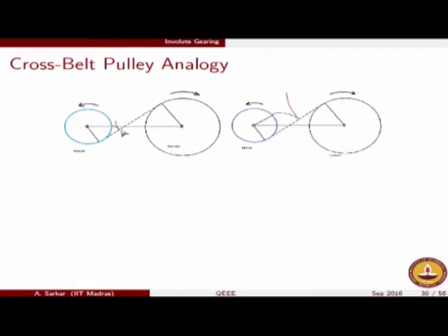For the red part of the curve it is just the opposite. Instead of unwinding the string, here the string is getting wound up. On the driver pulley the string is getting wound up, which is what you will see. As the string is getting wound up, it is just the reverse motion, if you like, and it is going to generate this red curve. So if I now put this pencil fixed onto a fixed point on the belt, and put this piece of paper on the driver pulley, that is this black pulley, let us see what curve is getting traced out.